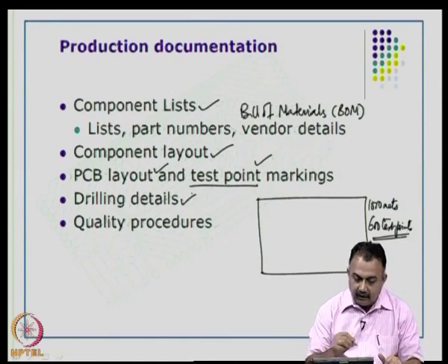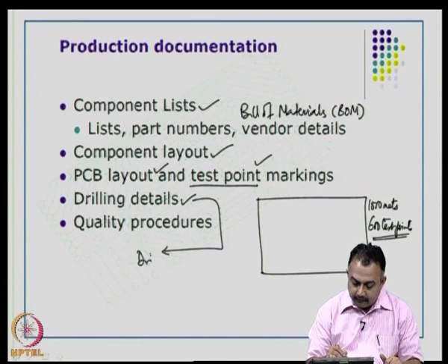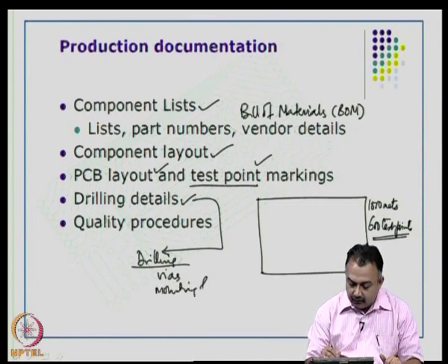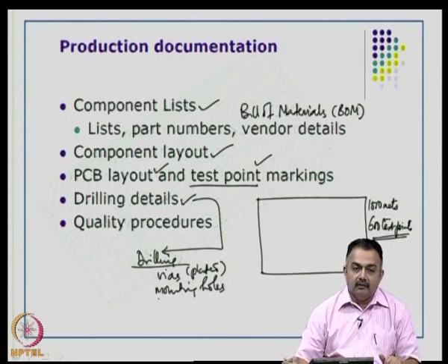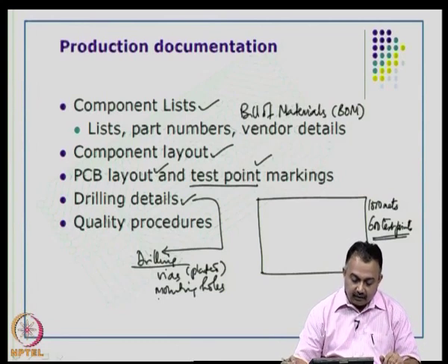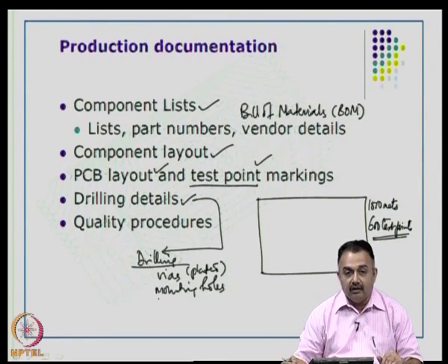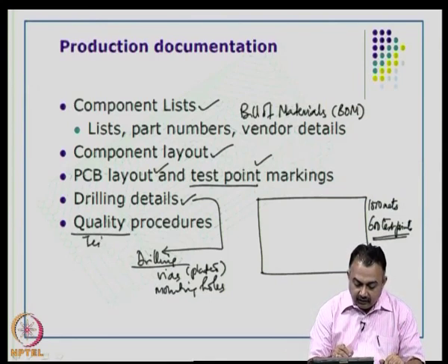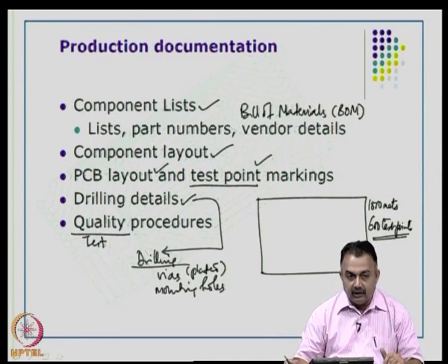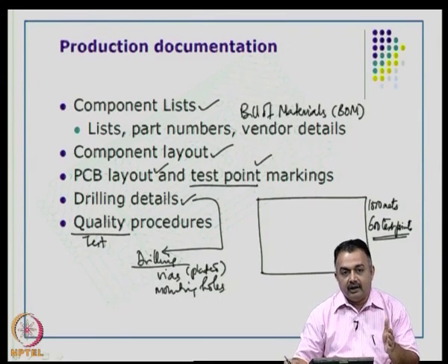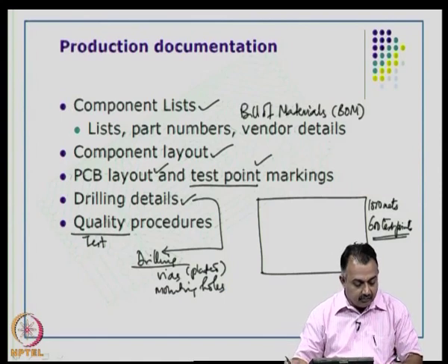And as I said earlier, documentation for drilling, because when you do a drilling process, there may be various vias that you are going to generate. Some are mounting holes, as I said, not necessarily to be plated, but these are plated to interconnect different layers, and in some cases there may be special cutouts that may be required for physically mounting your board onto the chassis of a product. All of these are done in the drilling process, and those details need to be documented, and the quality test procedures have to be followed. For any good industry that qualifies itself for high quality PCB fabrication, at every stage you have a quality check, right after drilling, right after imaging and so on. So, we will see about that when we come to the fabrication process.